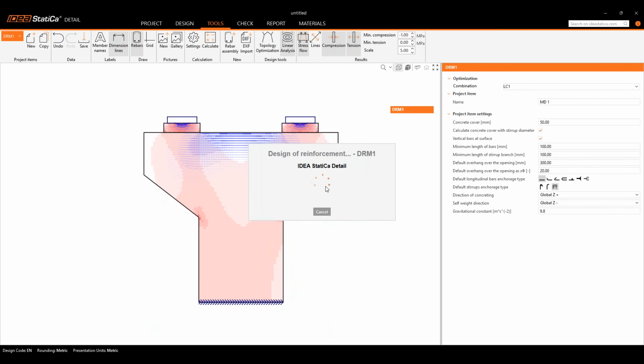So I'm going to run topology optimization. Just bear with me for a few seconds. It actually takes about 30 to 40 seconds to run the analysis. So with topology optimization, based on the input loads that we have just now, and based on the geometry of the structure that we laid out in our model, it gives you actually the precise alignment of, I would say, the compression and tension fields.